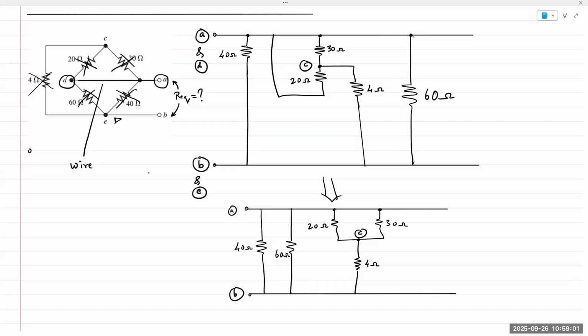Sometimes it does get tricky, especially when we learn circuits for the first time, or if you have not touched upon circuits for a long time. We look at a diagram and then there's different nodes and the different nodes are separate. But the concept that I want students to retain is that if there is a wire between 2 nodes, then it is the exact same node.